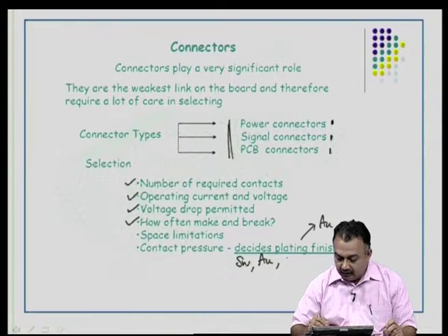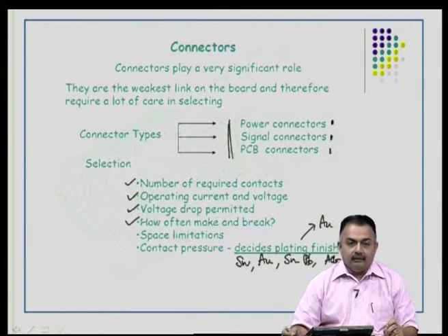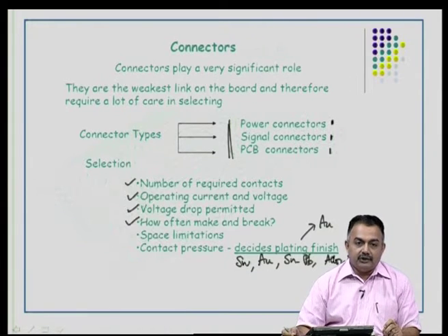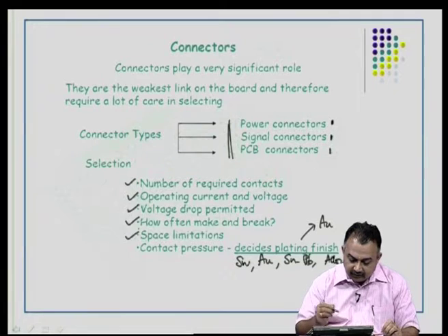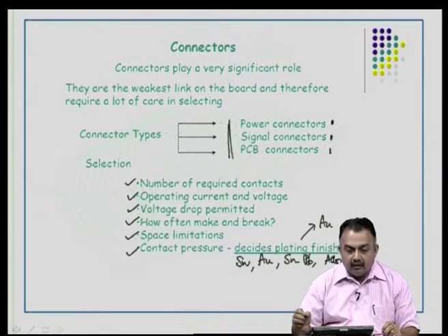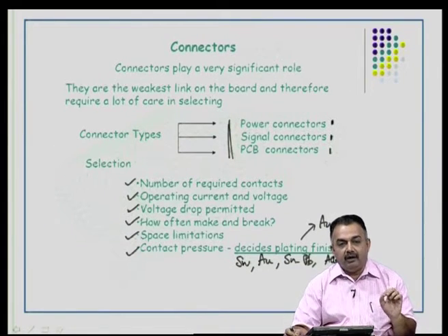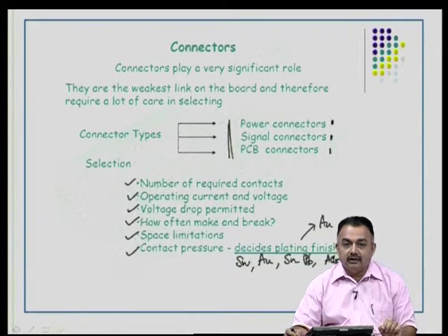Earlier, we were also using tin lead plating finishes, and other things like alloy 42 and so on. So, obviously, there will be a wide choice. You have to choose the connector based on the space limitations and the number of times you are going to make and break a circuit using these connectors.